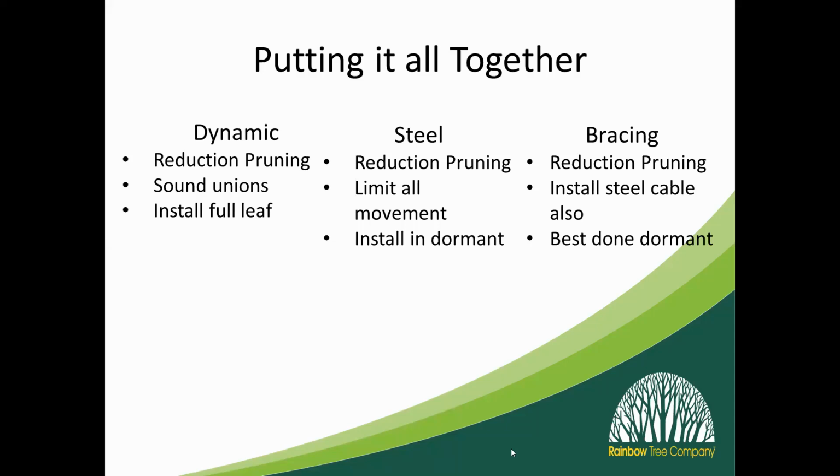And then also we need to be installing a steel cable with a brace. The brace itself is great, but the steel cable being higher up is going to give it that advantage on that leverage to hold it in place. The bracing is really just to hold that cracked section from cracking any farther.